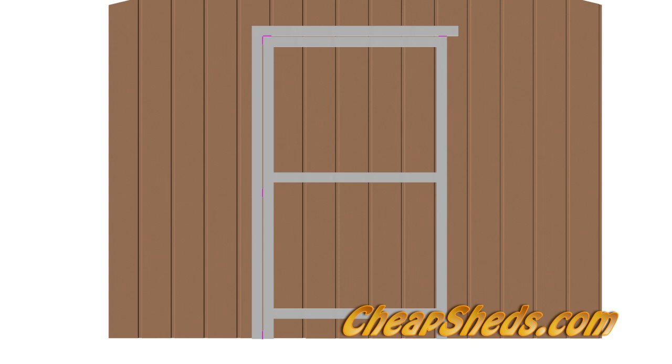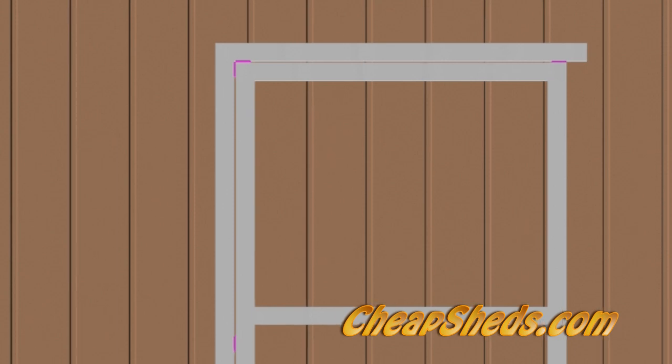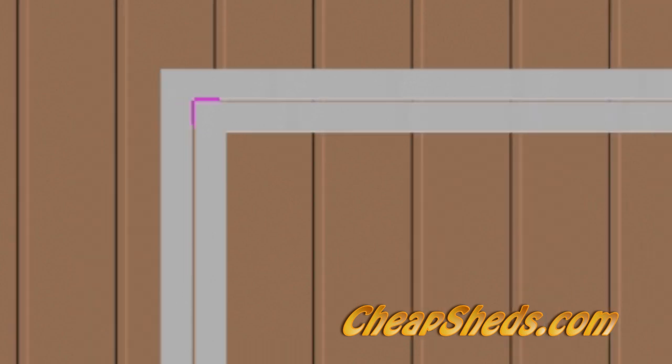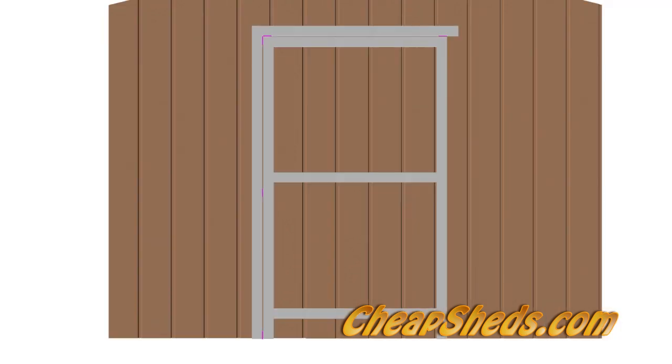Measure and cut the vertical piece of trim so that it extends between the bottom of the siding to 7/16 inch above the top edge of the top horizontal trim as allowed by the spacer. Nail this in place along the center of the trim. Move the 3 spacers to the other vertical trim piece and measure and cut and install the same way. Then measure, cut and install the horizontal piece across the top of the 2 vertical pieces you just installed.